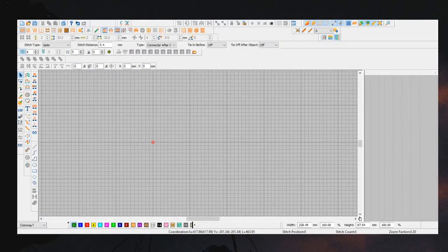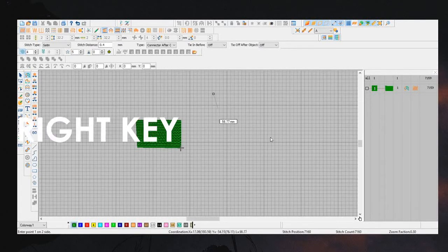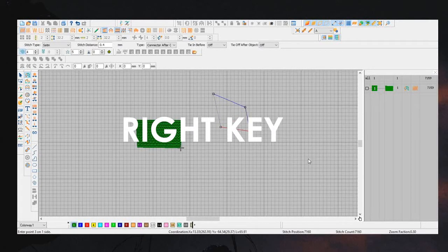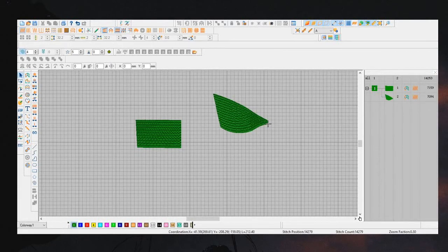One of the most important things that we need to know is the use of mouse. Basically, the left key is used as the main input method. You use the left key when you're creating an angular or straight type of point and pattern. On the other hand, when you're inputting curve control point, the mouse right key can be used. Just press enter when you're done inputting your pattern. Now, to locate the pattern properties that you've just created, you may double-click the pattern using the left key.